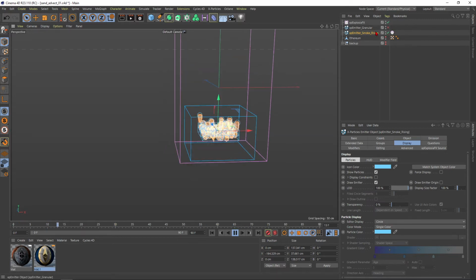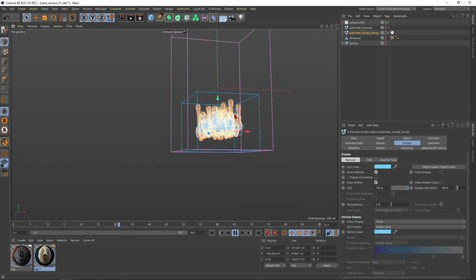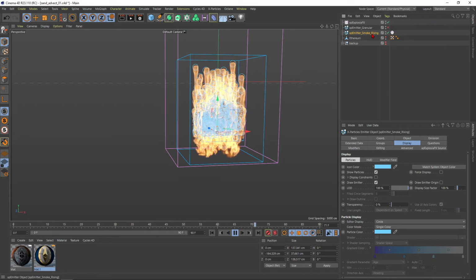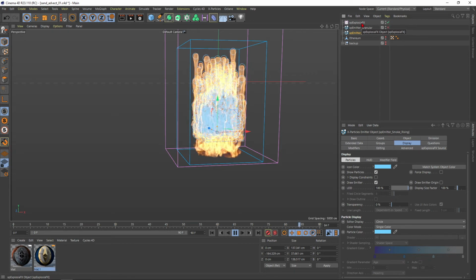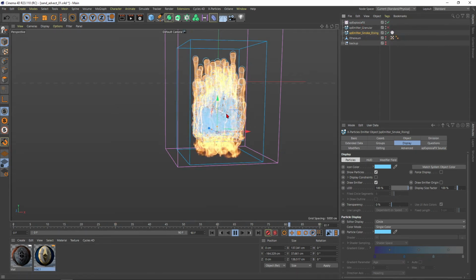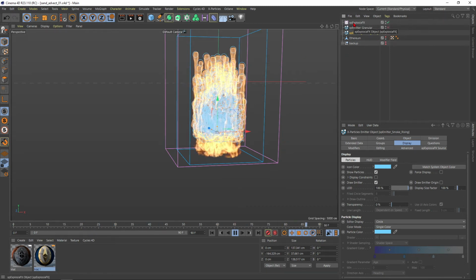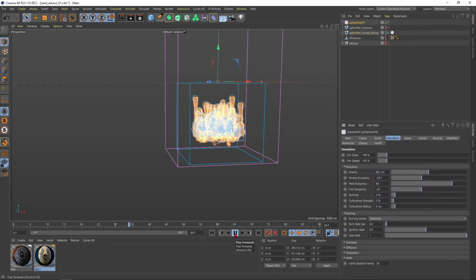So we need to make this a bit more interesting. So I think first what is going wrong here is that the fire is also going down. And I think that happens because these smoke rising particles shall not be affected by the exposure effects, okay? So we only want to have our granular or sand particles to be affected by that, but to have the smoke rising also affected by exposure effects doesn't make any sense. So just go to modify and exclude this one.